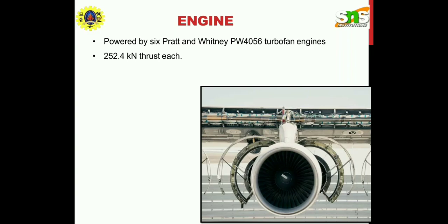And these are the engines powered by Pratt & Whitney turbo engines that will be used in the principle of turbo machines. When the path of the flow is wholly or mainly parallel to the axis of rotation, the device is termed an axial flow turbo machine. The radial component of the fluid velocity is negligible. Since there is no change in the direction of the fluid, several axial stages can be used to increase power output. A Kaplan turbine is an example of an axial flow turbine.